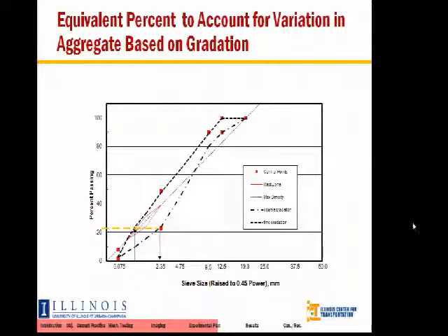Okay, about 22 to 25% passing. We want to take the same percentage so that we're accounting for the same quantity of aggregate in the coarse mix. And that actually gives us a minimum aggregate size to focus on of 2.36. Okay? Hopefully this makes sense to everybody.